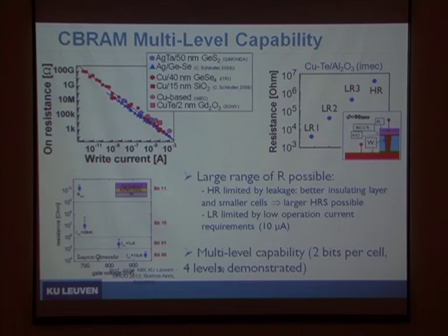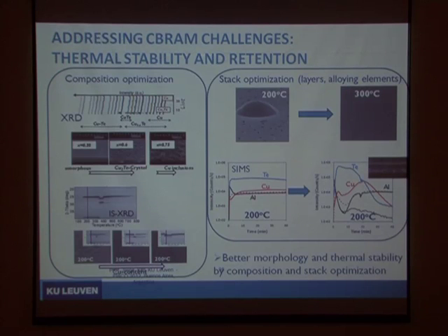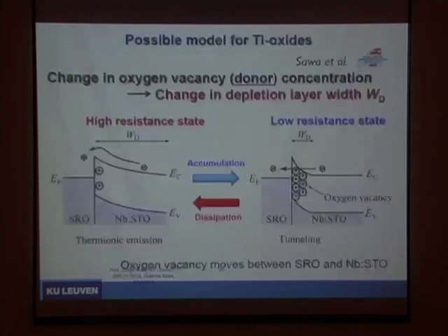So this is not too interesting. It's a very scalable technology. One of the key problems: what's the key problem with CBRAM? You take a very high mobility ion like copper, so that it can move fast with low voltage. Then what happens when you heat it up? It goes anywhere, everywhere. So these things tend to have very low thermal stability. Our fight, not described here in detail, was with thermal stability: how you can make these things switch fast with electric pulses, but not degrade when you apply temperature. That's part of the fight. We'll not get much into that.